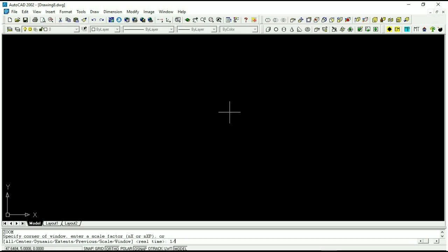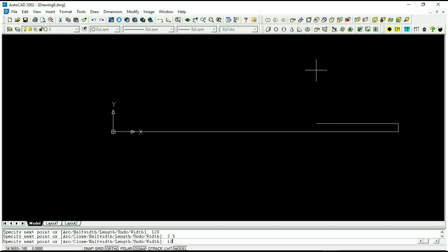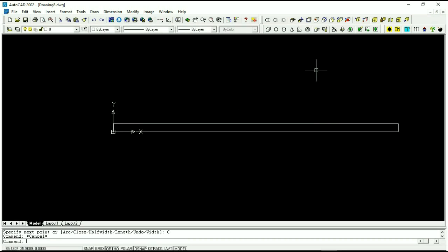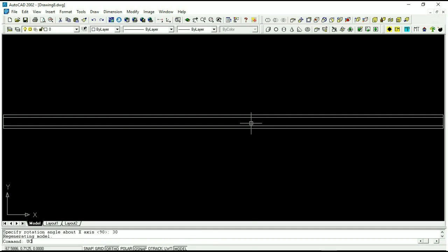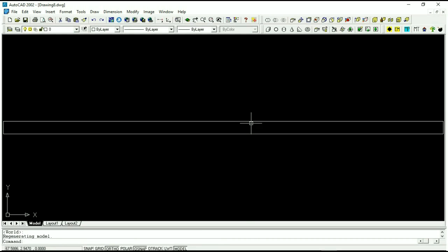And so now I'm going to make the plate. And I'm going to zoom out a little bit further. It'll be a 10-foot plate. And then I'm going to extrude it 3.5 inches, or 1.5. So if I do that around the X, hide, there you are. So the UCS is pretty, if you ever get lost, just type in UCS, it'll take you right back to the home position.